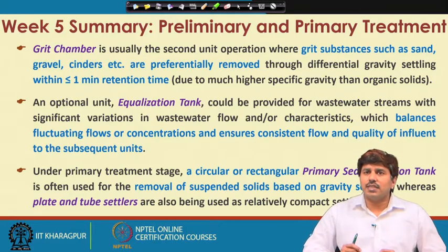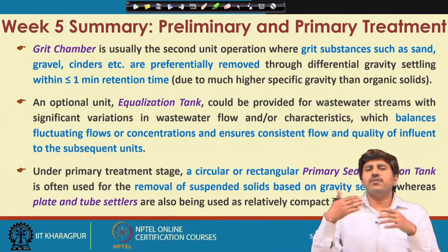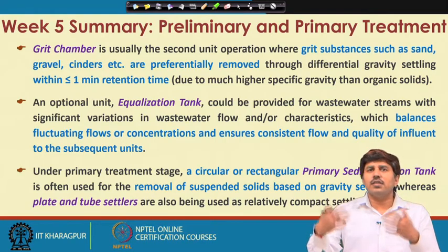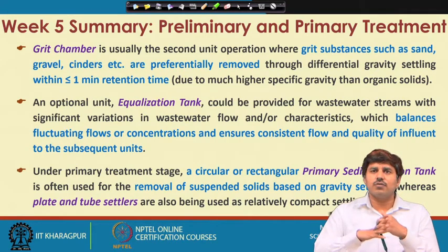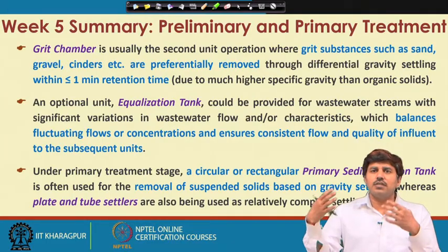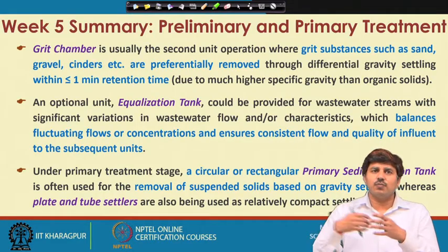So, if we see, the specific gravity of these grit particles is close to 2.65, because their specific gravity is much higher than the water. So, they quickly settle, within a minute we can get the removal of these grit particles through differential settling, whereas other fine suspended particles or organic suspended materials still remain in the suspension itself.